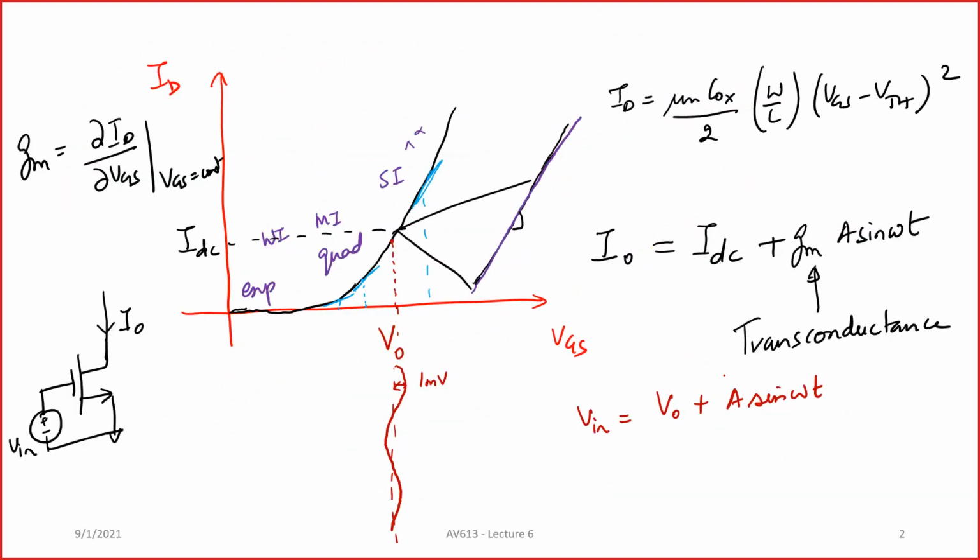So the deal is here. If you take the MOSFET as a 3-terminal device, assuming the bulk is also grounded here, you are setting up a voltage between two terminals of the MOSFET, which are the gate and the source. But this controls the current through a different terminal of the device, which is the drain. If you're talking about the current through the same terminal, or one of the two terminals across which the voltage is applied, then you don't need to use the word trans.